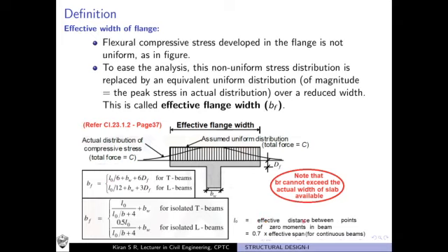So this is typically the span of the beam over which there is a huge change in the bending moment. You don't have to worry too much about it. If the value of L0 is directly given in the question, you just have to substitute it here. And if the given beam is a continuous beam, mostly the floor slab systems will be composed of beams which are continuous in nature.